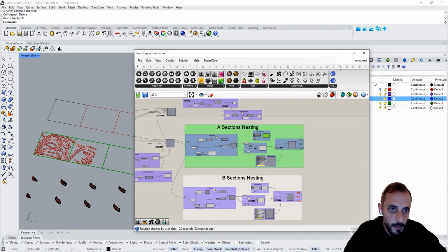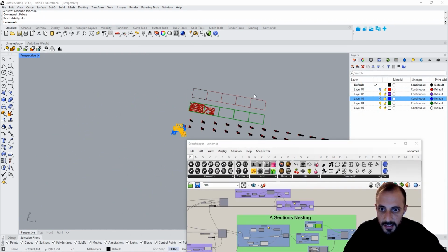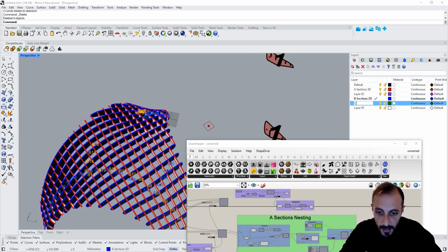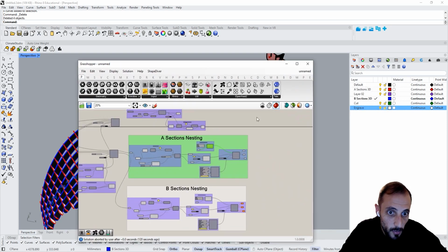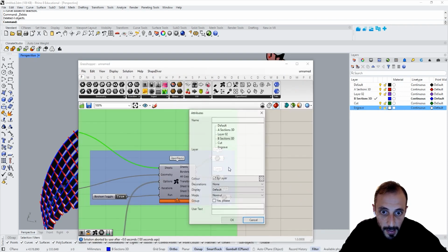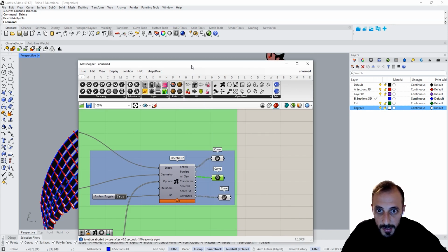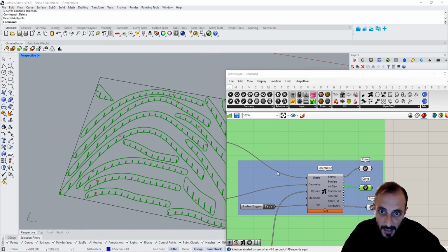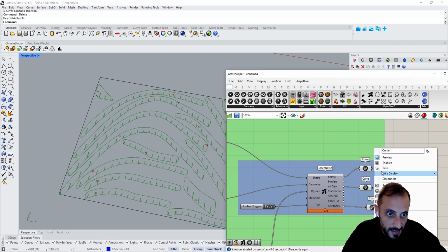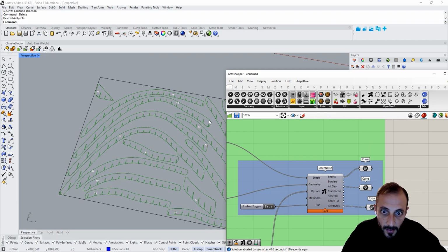And one thing I would be doing is the red pieces are A pieces, A sections, 3D, B sections, 3D, and cut, engrave. So my sheets are going to be in default layer, so I can bake them in default. All geometry, meaning I'll be cutting these, right? Bake them to cut layer and bake these attributes to my engrave layer, right?